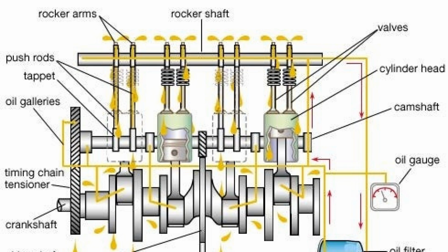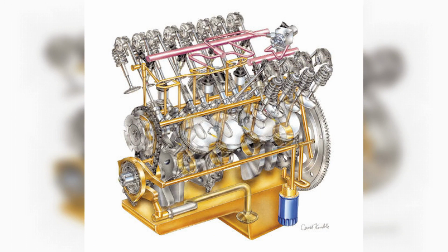Lubrication channels ensure uninterrupted, high-pressure oil delivery to rubbing mechanisms. Flow into the system from the pump is carried out through the main line, one of the functions of which is to provide lubrication of the crankshaft bearings. It should be noted that this is the simplest scheme of a passenger car lubrication system. Real systems can contain a considerable number of additional components that improve its performance characteristics.